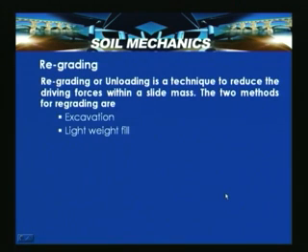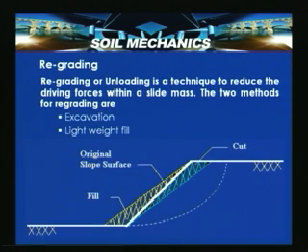So, regrading or unloading is a technique to reduce the driving forces within a sliding mass. The two methods for regrading are excavation and lightweight fill. Now, here is shown another option, where this portion of the slope was cut and removed, and then fill was provided here, which makes the slope slightly flatter.